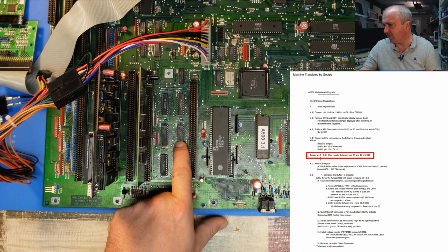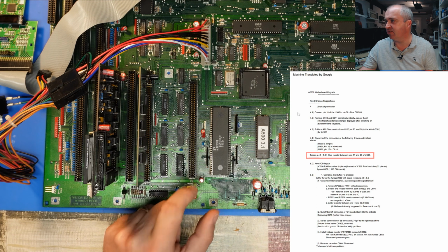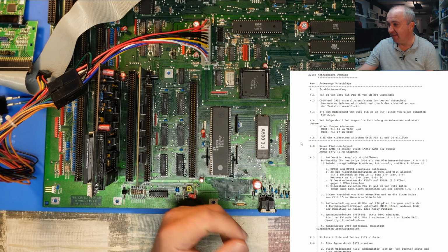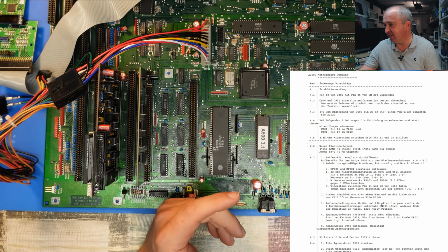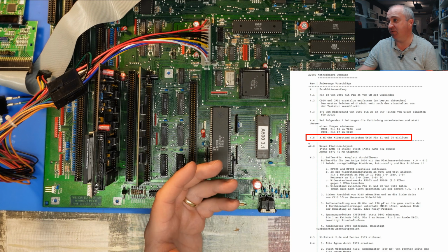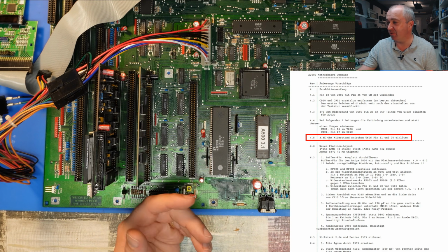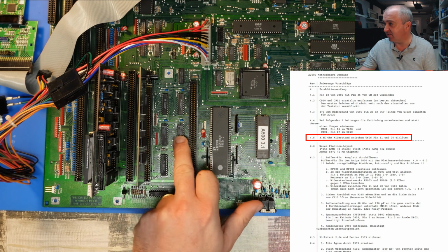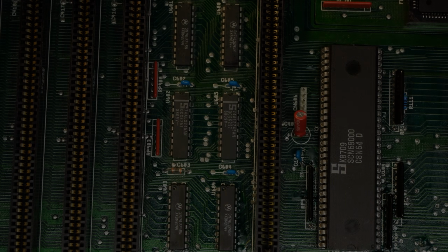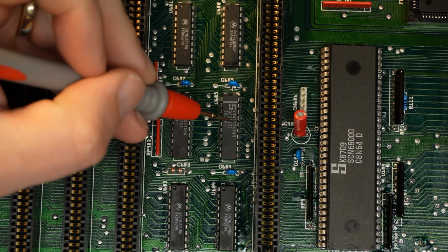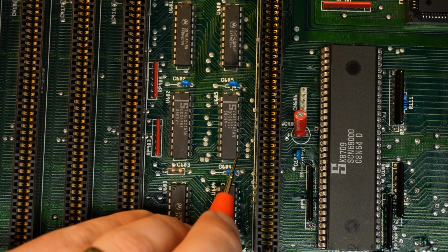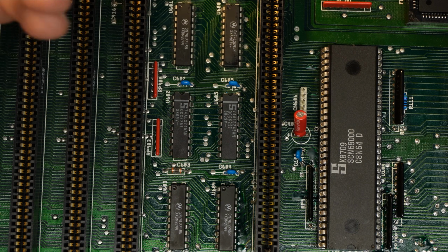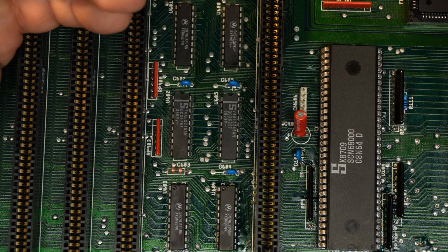Solder a 4.5. Where's the original document? Okay. Google Translate is getting itself mixed up a bit. So we are going to have to try and refer to both of these. But it's revision 4.5 and we need to solder a 3.3k ohm between pins 11 and 20 on U605. So between pins 11 and 20 of this chip, that's pin 11 down in that corner there, pin 20 being the last one, or 5 volts, so it's a 3.3k pull-up.